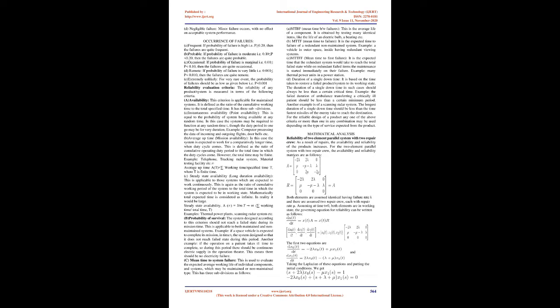8. Aging and wear out. This is not a primary cause, but it reflects prolonged exposure to other causes. 9. Substandard or defective parts. This is due to poor quality control. 10. Operator or maintenance-induced error. This is also known as human error. 11. Corrosion. This is chemical change which weakens material. 12. Failure at the time of switching on. Some components have operating time and idle time. So, when these are switched on from idle state, at that time these have probability of failure, like light bulbs.